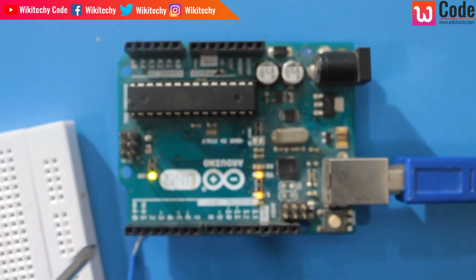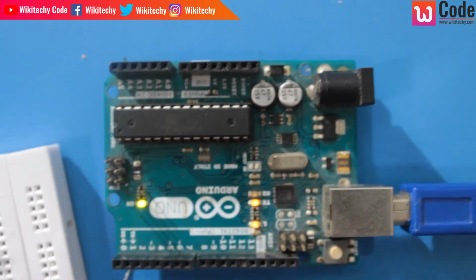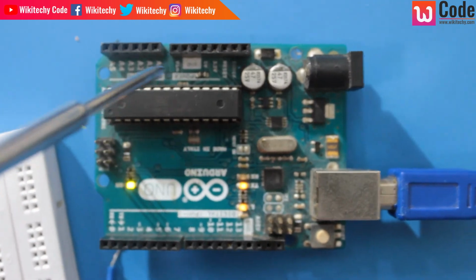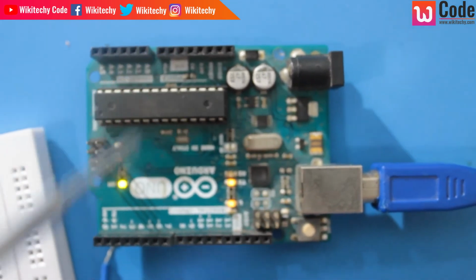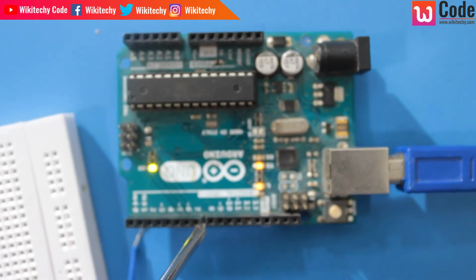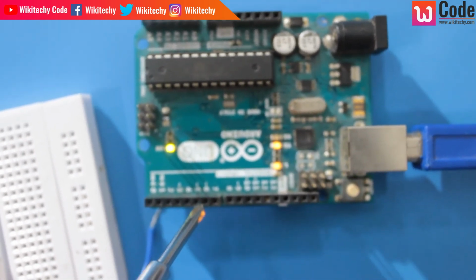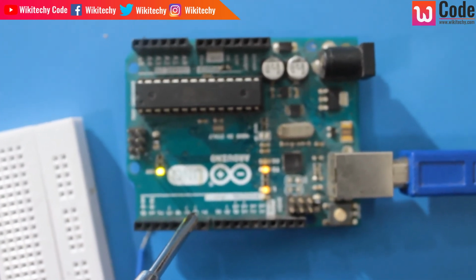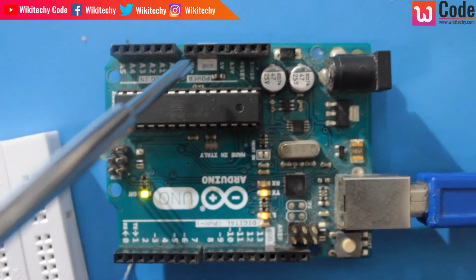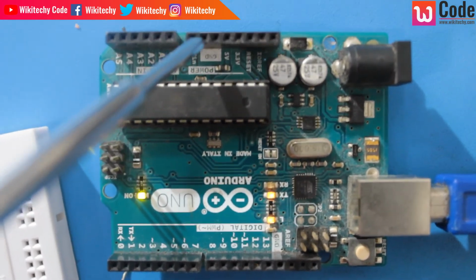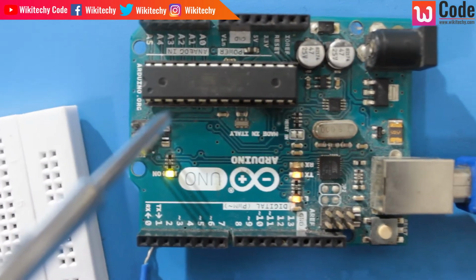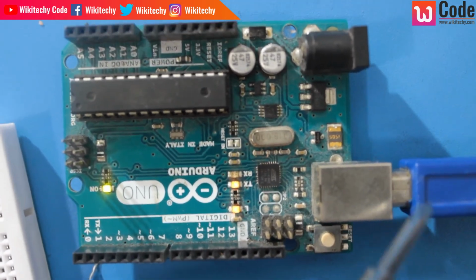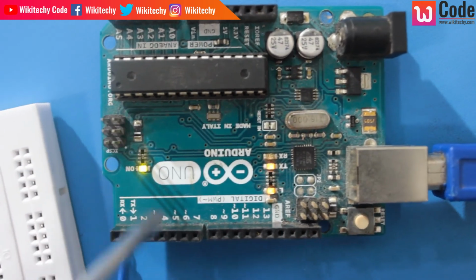Hi, this is your Arduino board. We are going to use it for our robotic motor control. Over here you are able to see the digital pins, and over here we got the analog pins, and this is the power supply. So we are going to take the pin 8, 7, 6 and 5. So 4 pins we are taking to give the input and output from Arduino board, and apart from that we need the 5 volts for the power supply and ground to make the circuit to be grounded. So this is your microcontroller, and from here it's connected to the computer. From the computer I am trying to connect and control the Arduino board.